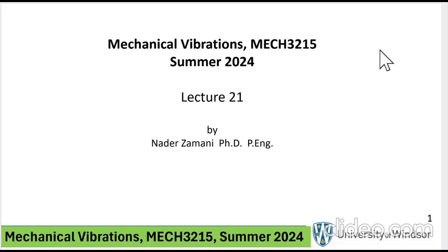So I did the free vibration for you, no damping, and the key point was to be able to use a modal matrix to decouple these equations. Once they were decoupled, every single one of them became similar to what we had done in the first 6-7 weeks of the course, namely a single degree of freedom system.